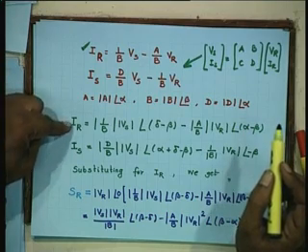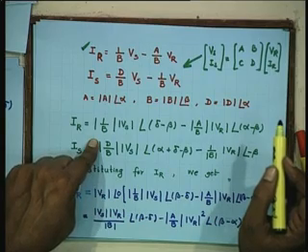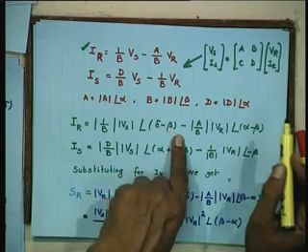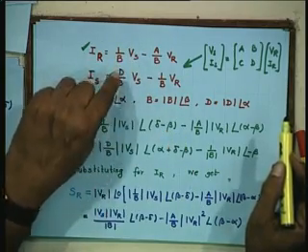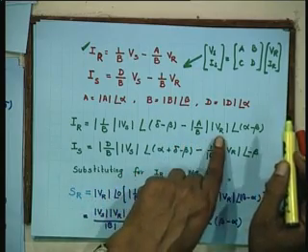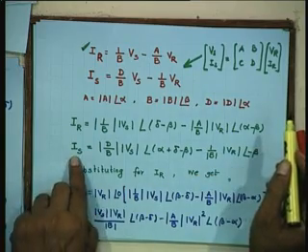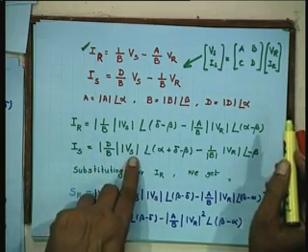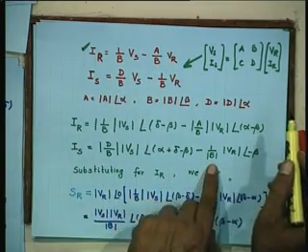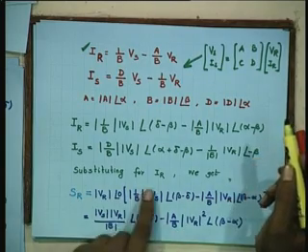All right. So, this IR and IS, now you substitute magnitude and angles. So, you will get 1 by B magnitude, Vs magnitude, delta minus beta, because this is delta and this is beta. So, where beta when goes upstairs becomes minus. Similarly, minus A by B, Vr, A is alpha, B is beta. So, alpha minus beta. Is D by B, Vs alpha plus delta minus beta minus 1 by B, Vr beta is only minus beta, because 0 minus beta is minus beta. Substituting for IR,